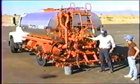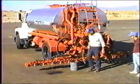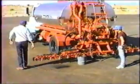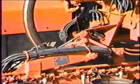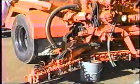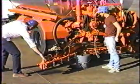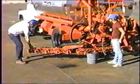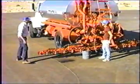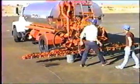I'll do this in the down position. The wings have a shear pin right here on the swing joint, and if we run into something with this wing, and sometimes I'm tough enough and sometimes I'm not. There, I did it that time. If we run into something with that wing, it shears that pin and the wing gets out of the way. Okay? And it'll do that either direction. It'll go forward or it'll go reverse. It'll get out of the way.